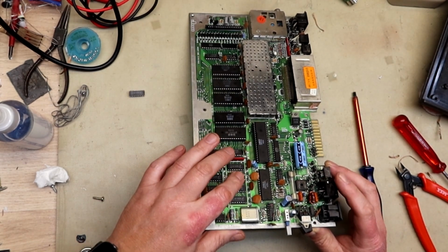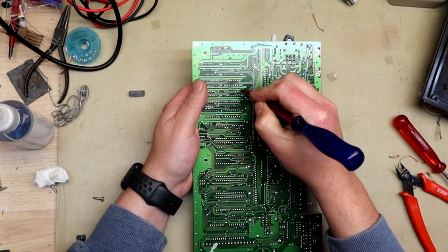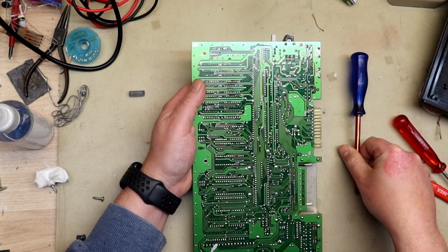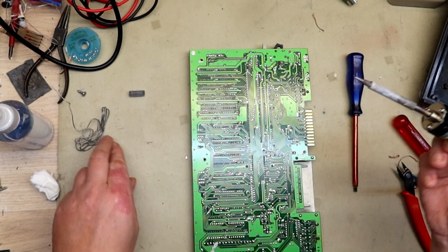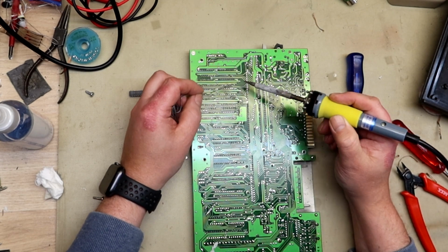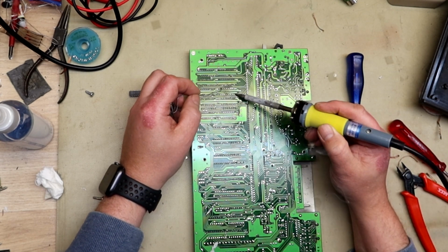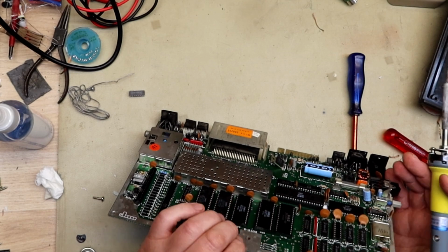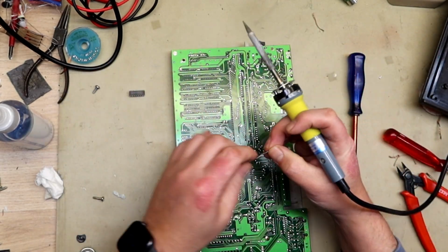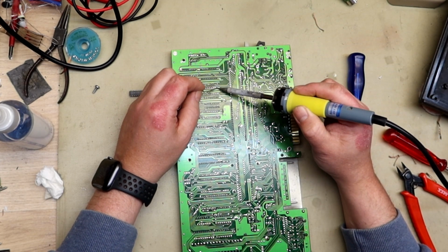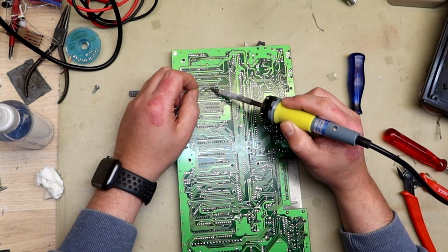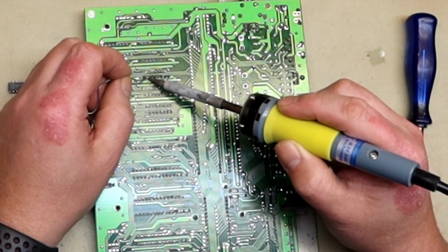Yes, when everything is cleaned up, it's about placing the sockets and soldering them in. And my way of doing that is that I push in the sockets and I bend two or four of the legs to keep them in contact with the PCB when you do the soldering. Many of you use gum or some other fancy tricks to do this. You can also support the socket from behind so that you keep some weight on it, but I think this works quite okay.